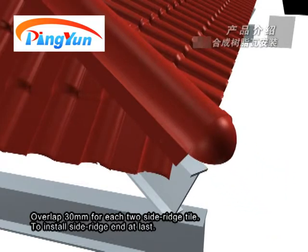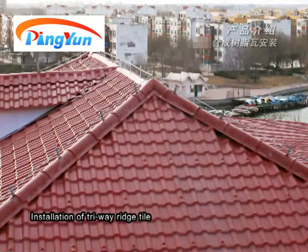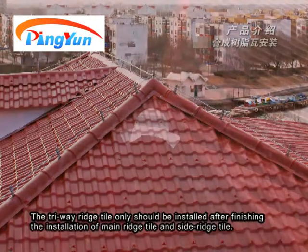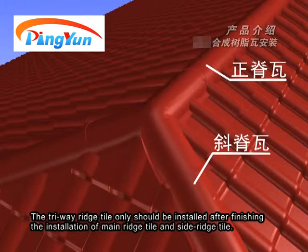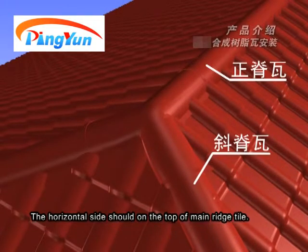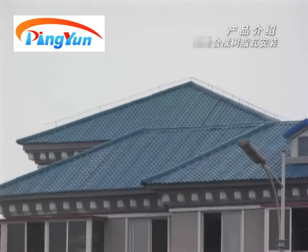To install side ridge end at last. Installation of tri-way ridge tile. The tri-way ridge tile should only be installed after finishing the installation of main ridge tile and side ridge tile. The horizontal side should be on the top of main ridge tile.